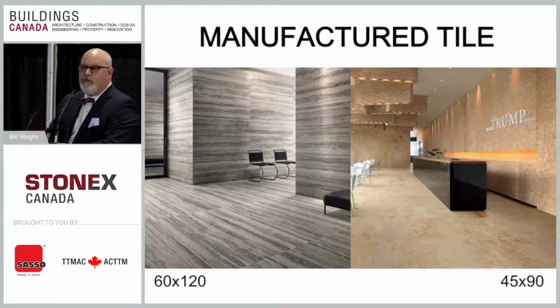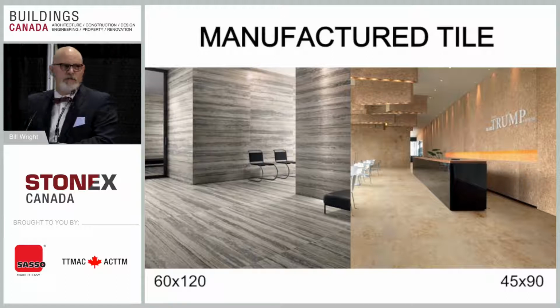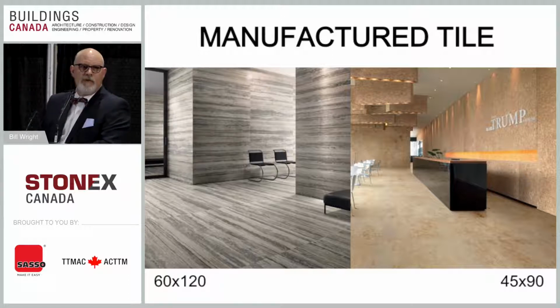There's always going to be some preparation. The best thing the cement guys can do for a flat floor is about 6 millimeters in 3 meters. And as I said earlier, we need somewhere between 2 and 3 millimeters. So you already see that there's going to be an issue in terms of how flat the concrete guy can get the floor. So there's always going to be some type of prep required to make sure things are flat enough to install tile.